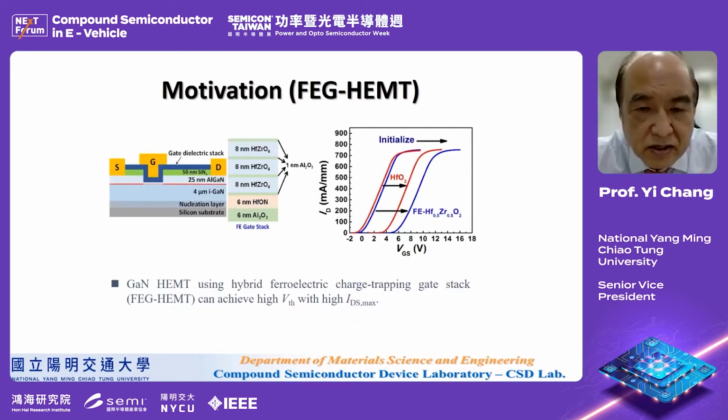This is the cross-section of the device. You can see that we have multi-layer hafnium zirconium oxide on top of aluminum oxide and hafnium oxynitride, and then gallium nitride.